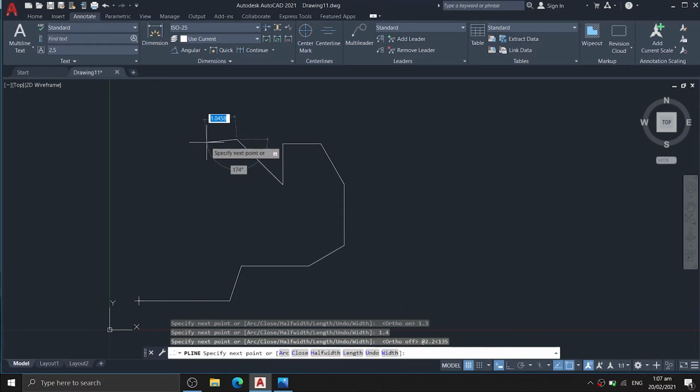Again, we have a straight line to the left having 1 as its distance. And then a 1.5 distance with an angle of 225 degrees, which we get from adding the given angle of 45 degrees to 180. So we will type at 1.5 tab 225 degrees angle. Enter. And again, a straight line to the left having one distance also. So type 1.